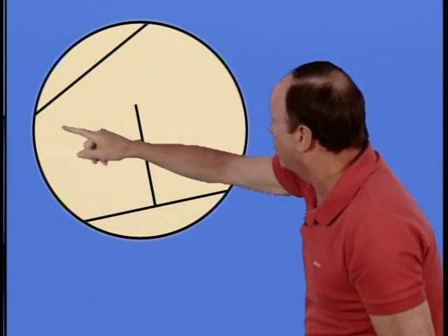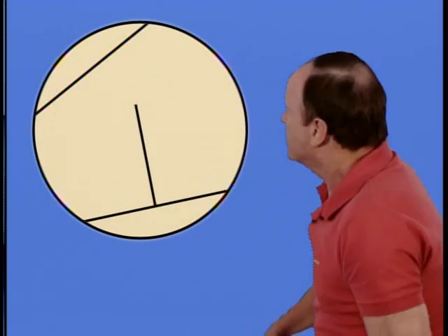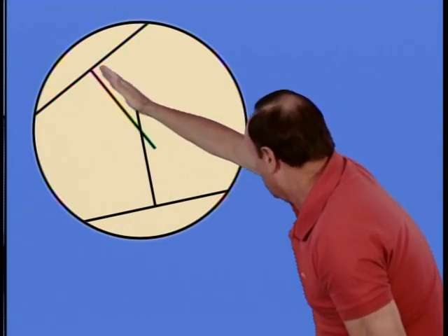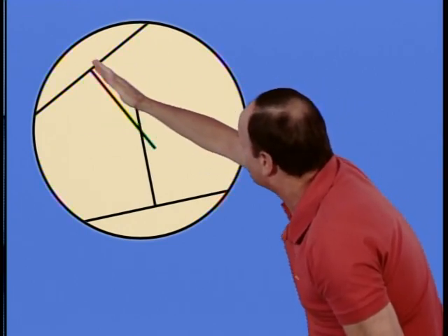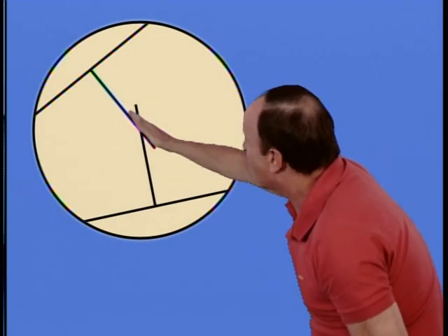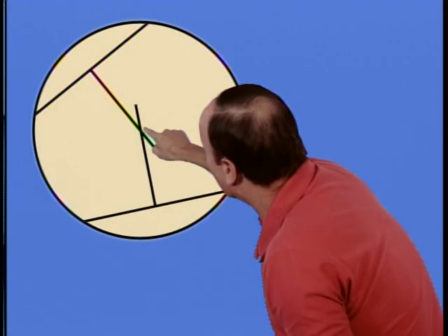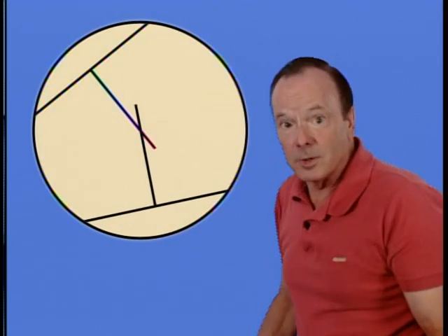You have to have two of them so you can have the lines intersect. So you take the second chord line and draw a line halfway between the edges of the chord line, and it's perpendicular, and now you have a second perpendicular line, and the intersection of those two lines makes a point, and right there is the center of your circle.